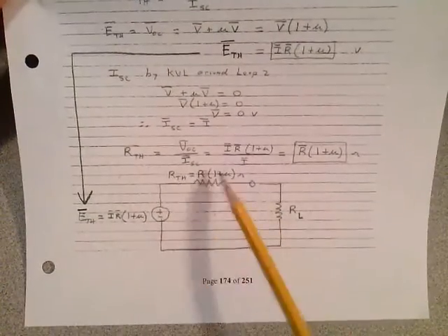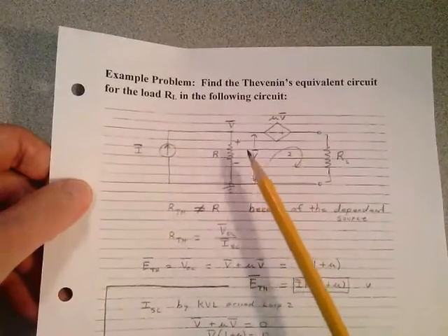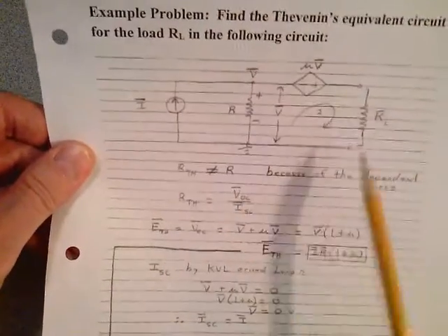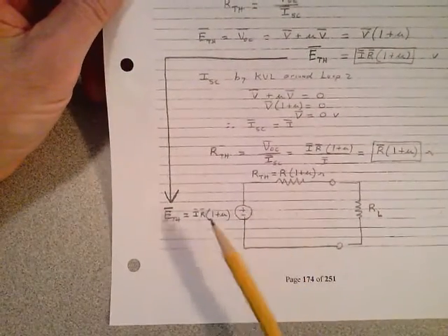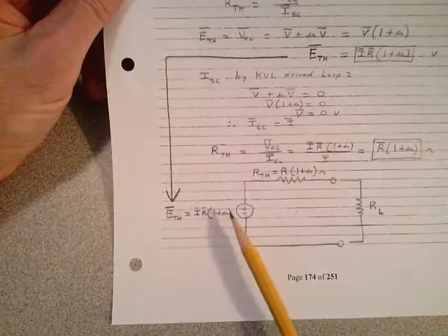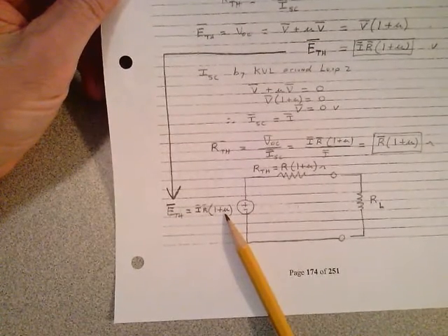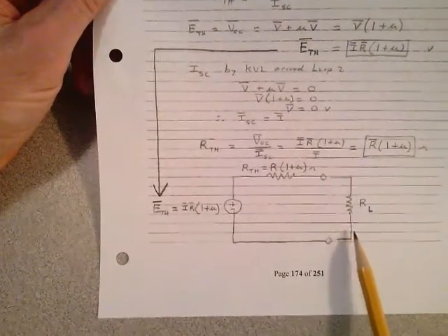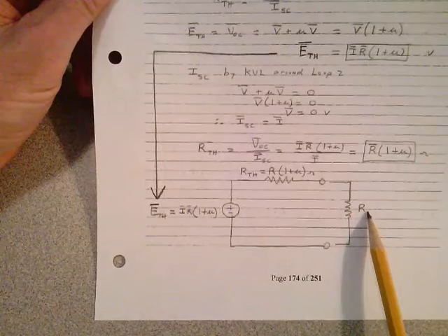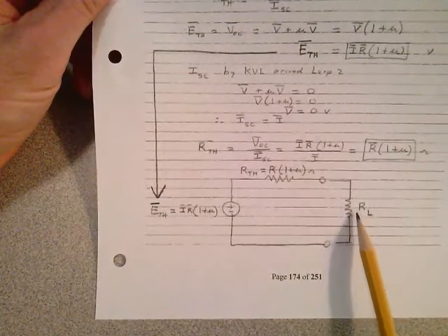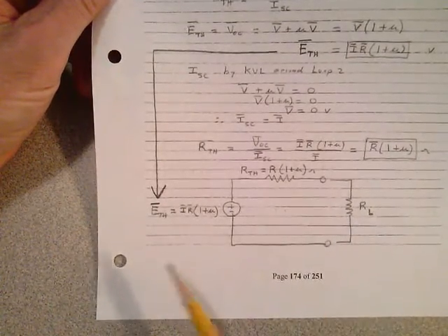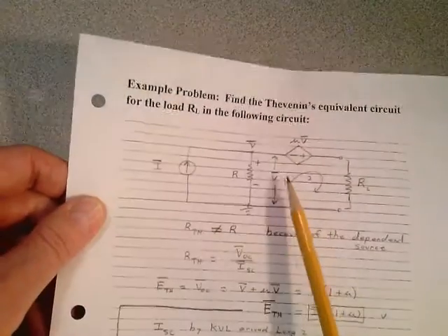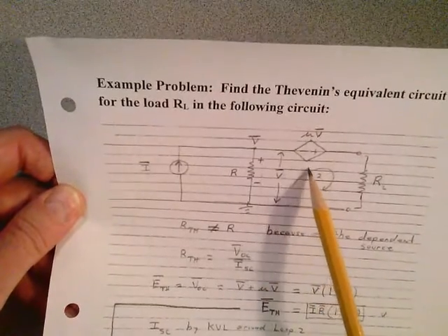Now, that's a general circuit model of that active device up here for different load resistors. If you know the current I, the value R, and mu for a particular type of active device, you can calculate either the load voltage or the load current for different loads. For 100 ohms, for 1K, for 10K. It makes it a very simple series circuit problem, as opposed to doing this for 4 different resistance values up here.